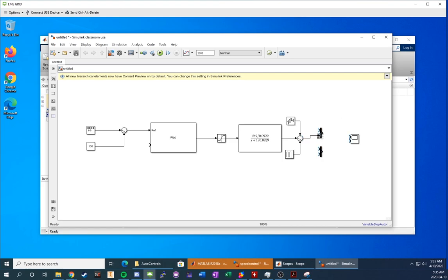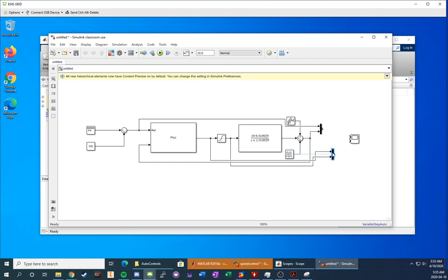In this case, we're going to have our omega up here, coming back to look at both the reference signal as well as what the omega currently is. We're also going to need to take the feedback loop here, being the current position, being fed back to the PI controller. This mux here is going to look at the signal coming from the saturation block, on both sides of the saturation block.